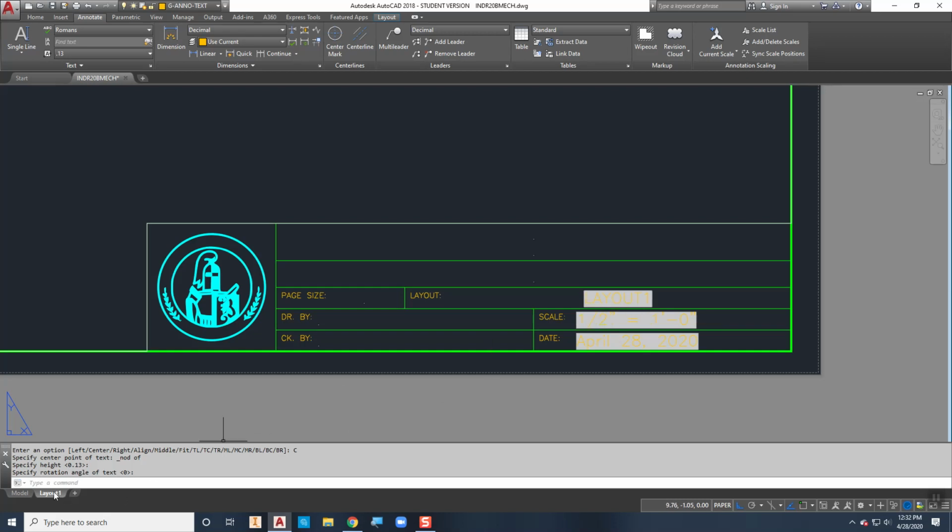And again, just like I did with the scale, if I come in here and I change the name of this to say, oh, we don't want to call it something architectural. We could call it sheet 1-2020, just to give it a longer name. Okay, it doesn't update here until I do what? Oh yeah, that's right. I have to regen and get it to think about it. And so now it says sheet 1-2020. So whatever I name them down here, it's going to be named up here.